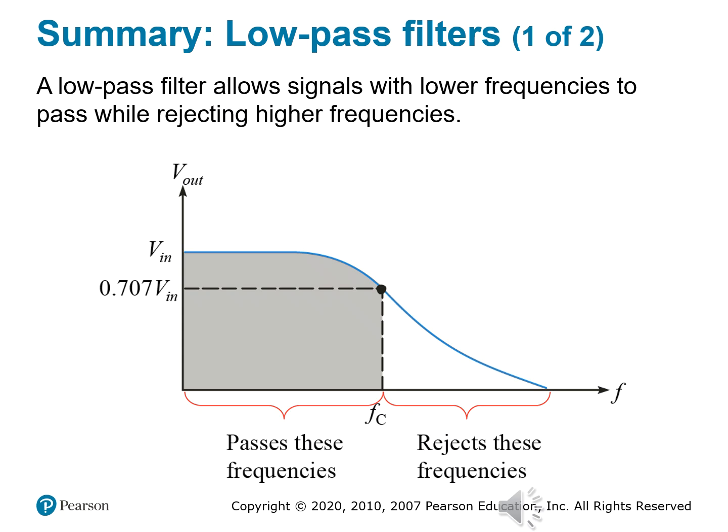So as you can see in the graph here, the filter maintains a consistent output V sub out for the lower frequencies, but as the frequencies climb past a certain point, something interesting starts to happen. At the cutoff frequency, that you see is labeled V sub C, the output starts to roll off. It's where the high frequencies begin to get attenuated, or in plain speak, they just get turned down.